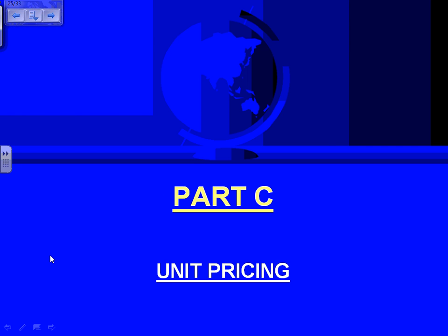So if you guys go with me, please, my friends, let's go to page, and this doesn't take that much, guys, just one page here, all the way to page 83. If you look at page 83, they're trying to find a unit price for a temporary wiring. You look at the structure. They basically have a 100 amp panel with a meter mounted on a wood structure where you throw it in the back of your truck, Ashley, and every time you go to a new job, if it's a smaller job, you take it from your truck, you mount it, ground it, bond it, bring the service to it, and off it goes with temp wiring. Cool? That's what they're doing, a unit price.